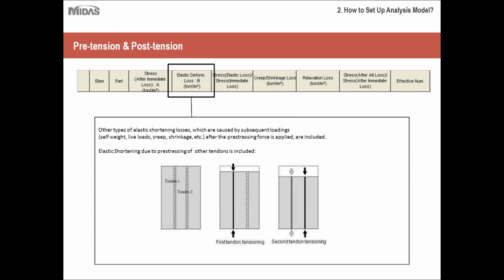So you must account for these types of elastic deformation, because in splice girder bridges this is a phenomenon that will definitely occur as you are post-tensioning a prestressed section, and you have to account for all these other effects.